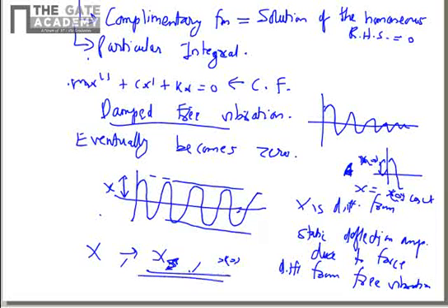However, it is a combination of these two because both of the components are working here, and it will also depend on the damping. Due to damping the displacement will lag behind the force, and this lagging is controlled by how much damping you are providing. After you provide the force, it will take some time for the displacement to happen in a damped system. So it will depend on damping, stiffness, mass, everything. And we are not worrying about the complementary function, that is the initial transient.